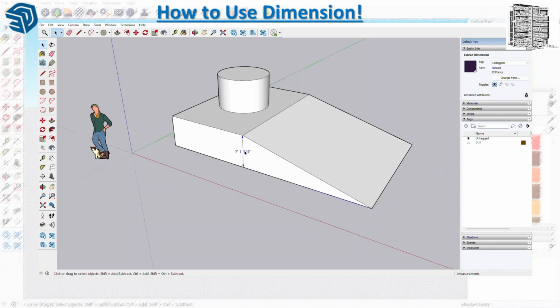You can also right click, and the next option would be Edit Text. Note here, or tip, if you adjust the text, it's not going to adjust the size or the dimension of the object. You're basically just adjusting the text. It's not going to adjust the actual size of the dimension, so just be careful with that one. The next one is going to be the text position. We kind of reviewed this one: up, down, center, outside, and then you just select them over here. You can go and adjust all of them in one area.